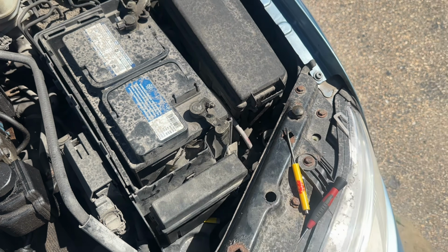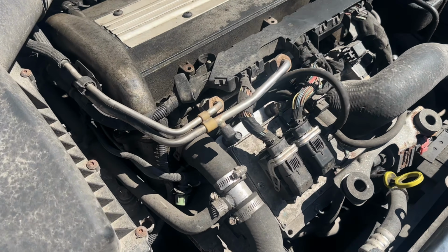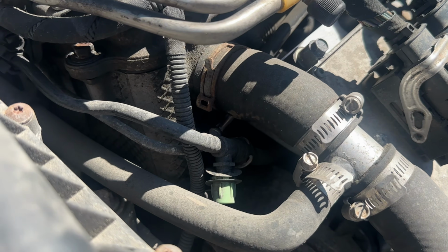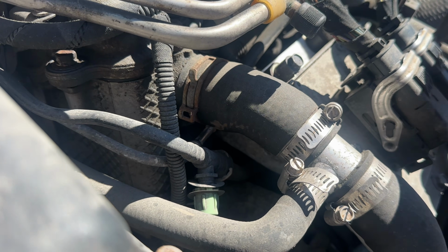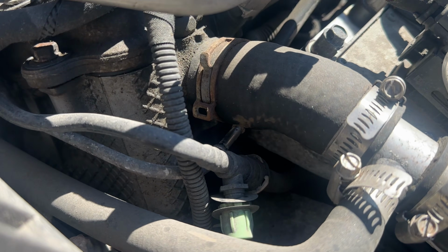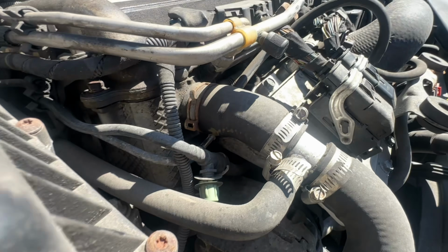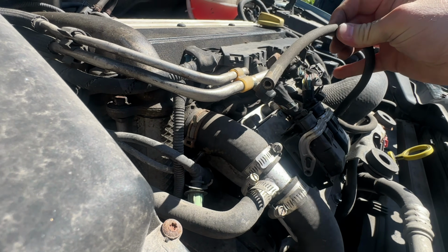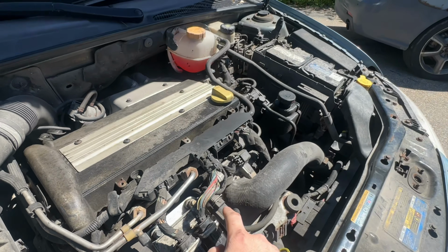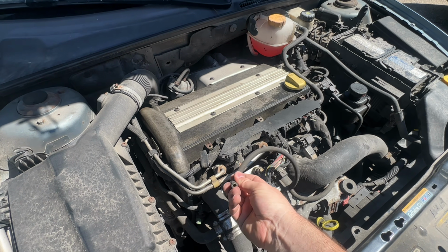As promised, let's also look into P0033. When I was messing around with the ECM for you guys, I noticed that this boost solenoid hose is not plugged in under the coolant pipe right here. This likely happened when I was replacing the ECM and the coolant pipe at the same time a couple of years ago. This is an example of one of those issues you cause and you rediscover when working on something else after a couple of years. So let's plug it back in and get it working again.